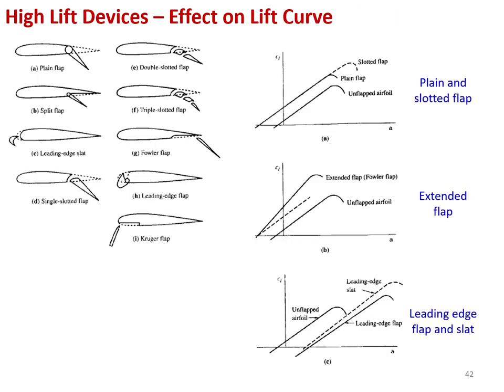Okay. So you can see a comparison of all of the different mechanisms with each other in this graph. For example, for the plain and slotted flaps, which are cases A and E, with the plain flap, we already know that the CL is going to increase, but the stall angle of attack is going to decrease.